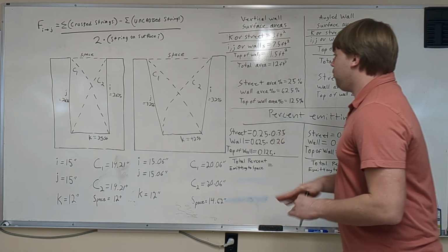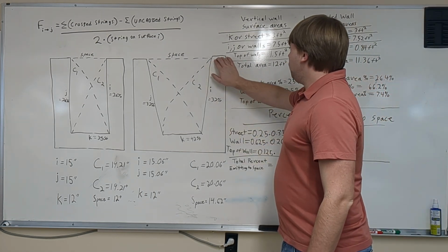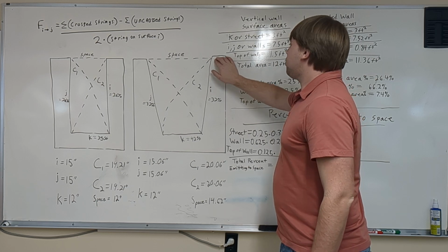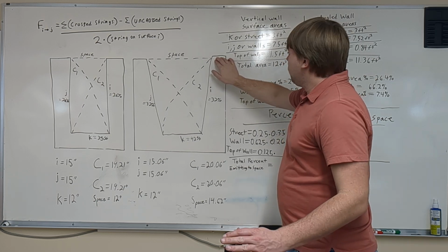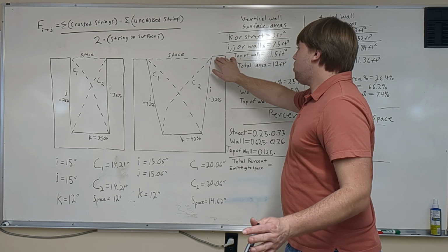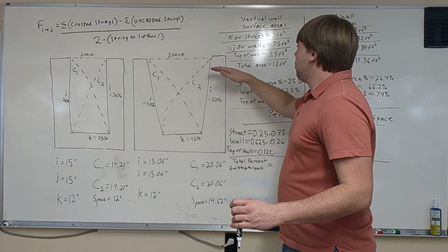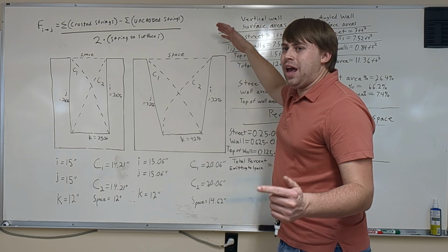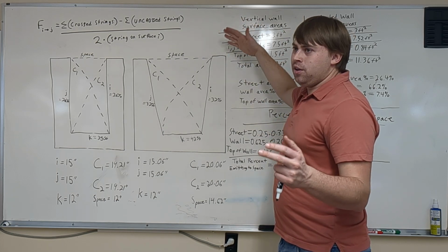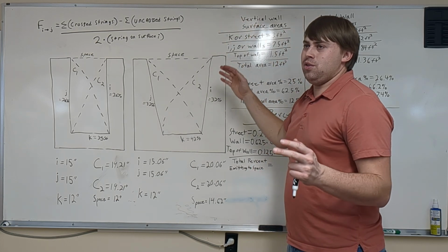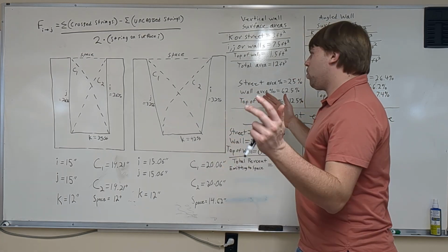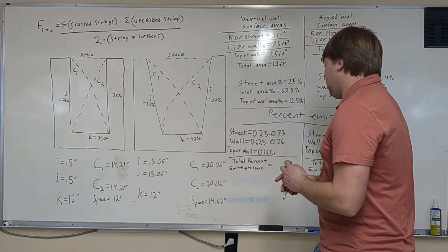Since we didn't solve for a view factor for the top of them, we assumed a view factor of 1. That's because we're making a reasonable assumption that this is the tallest building in the near area, so anything in its field of view would have to be the atmosphere, and therefore what we are considering to be a chance to go to space. So we're using a view factor of 1 for this.